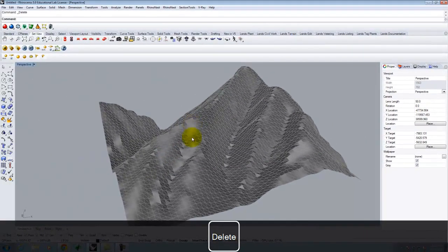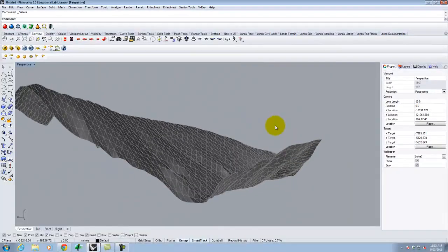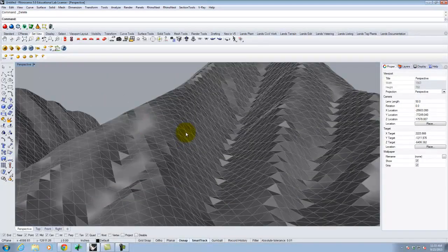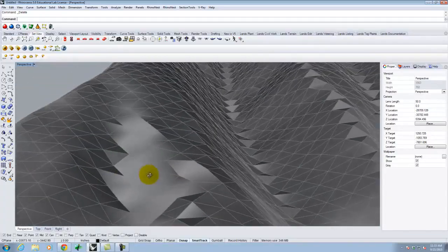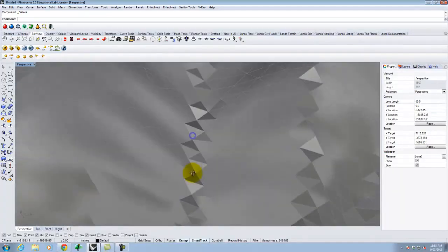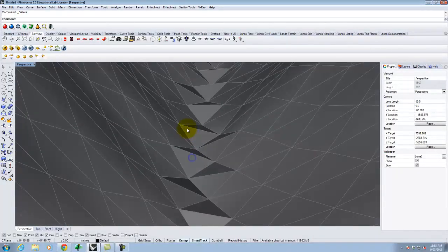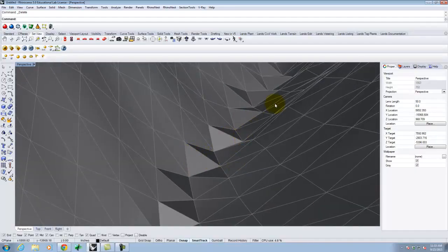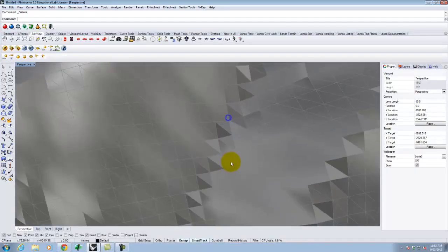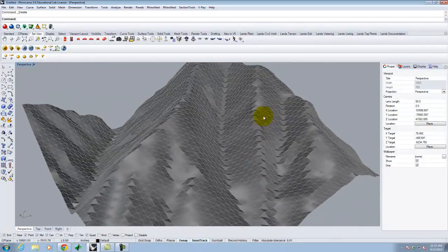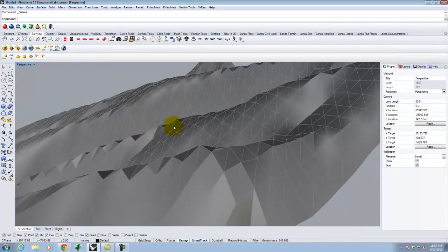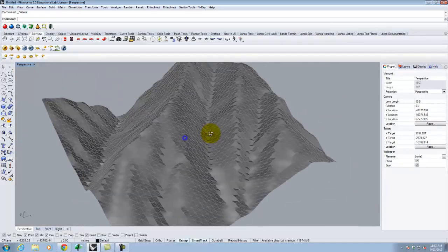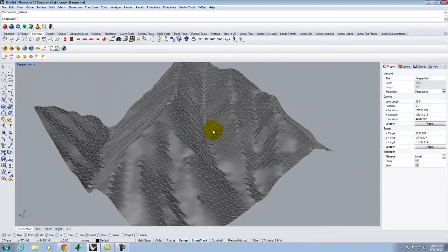And let's have a little bit closer look at the SketchUp file that is the terrain. So if I look at this, we can see that it's made up of a bunch of little itty-bitty triangles, right? And so if we look carefully in this valley, for example, we get kind of a jagged step pattern because of the nature of the triangles. Same thing on each of these ridges, right? In reality, the ridge doesn't have these little divots in it. It's a smooth ridge. So we need to transform this into a shape that we can really work with.